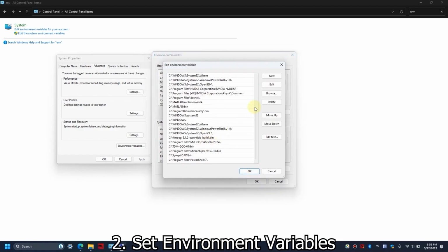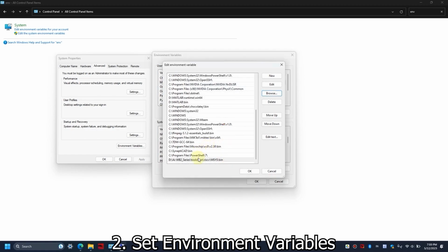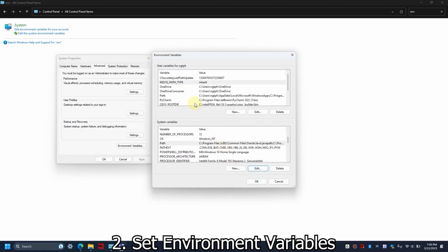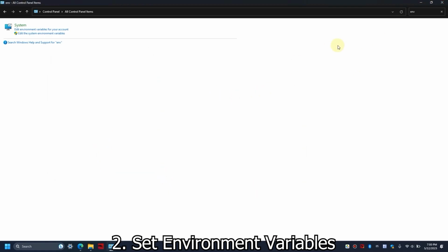You see a bunch of paths. Click new and then browse, and then choose the location of your SDK that you saved earlier. Here is the Ai-WB2 series here, to chain, msys, and bin. Here it is. Double check the directory, make sure it's correct. Press OK. Double check up here, MSYS2_PATH_TYPE. OK and OK. And you have finished setting up the environment variables.